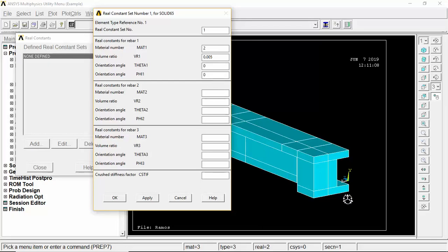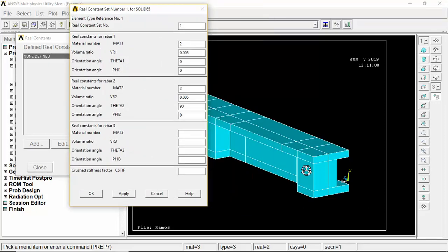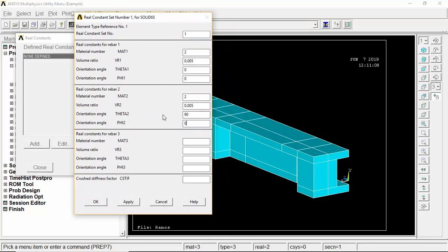Here I need sets of rebar along Y direction and X direction. And for Z direction, my pre-stress cables will work. Again, 90 for Y, and that's it. Also, sometimes, for example, your volume is not exactly along the main directions and axis, so you can define a local coordination system, and that will work in your local coordination system. I will discuss the local coordination system further.